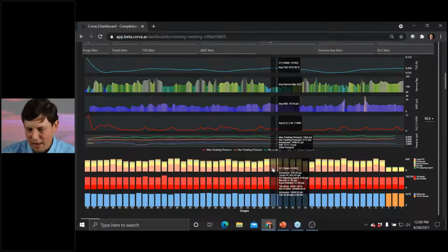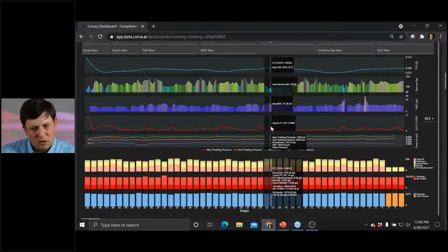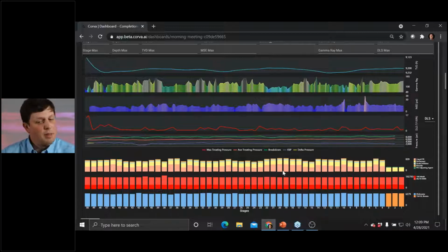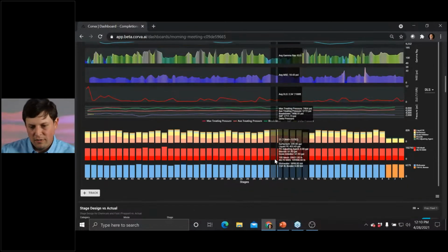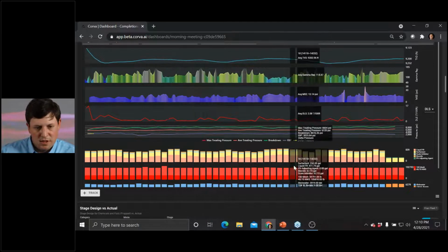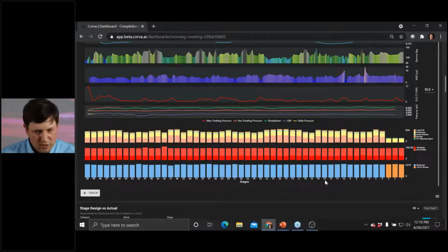And why was that? Outside of the previous app, where it's just showing you pressure and rate, I can actually correlate to drilling. So maybe I'm not out of zone, but MSE, gamma, my lithology actually indicates, hey, this is a lot tighter. Maybe I need to change my set points and tweak that so, again, I can get this job pumped away safely. I don't screen out. I keep operations moving effectively. So that is how customers have leveraged this, both in design and during operations as well. Outside of post-stage, they could see what's going on even after they pump. So if they have stages closer to the heel, they can alter what they're doing, and be more efficient, safe, and effective from there.